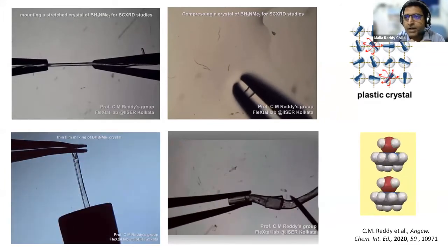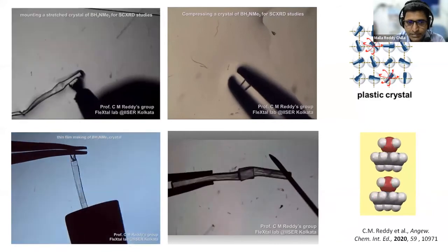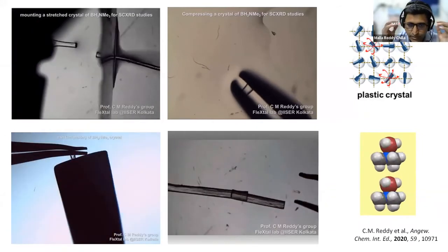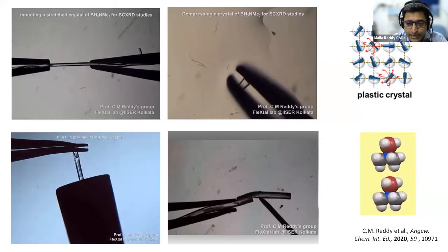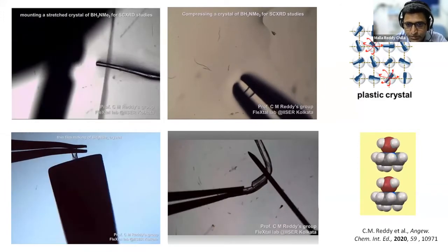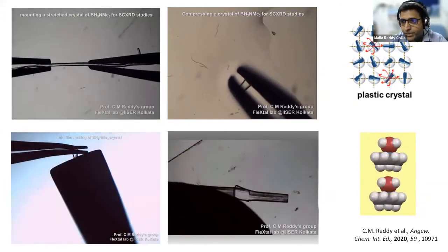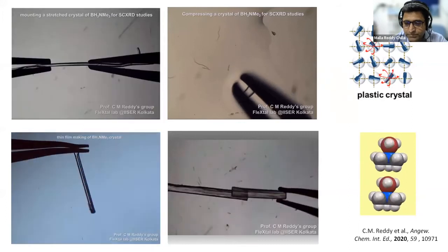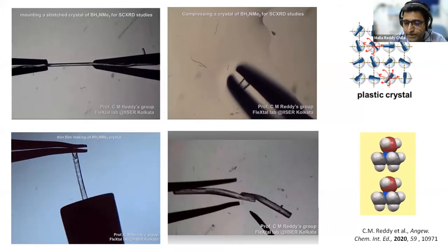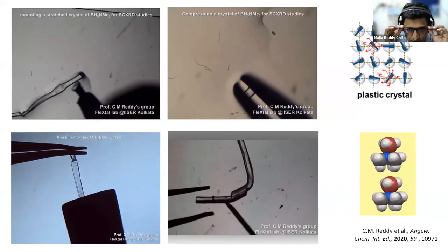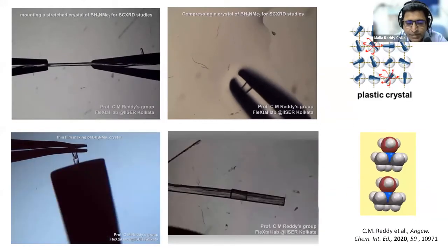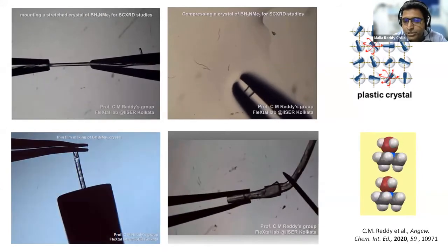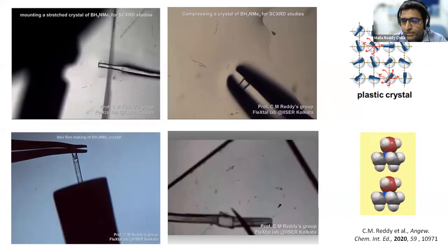For example, if you take a copper wire, unlike plastic molecular crystals, you can twist it, you can make a thin film, so they are very ductile, right? Highly plastic metals, particularly at higher temperatures, you can shape into any shape, but that was not seen in molecular crystals. Although people have studied certain crystals called plastic crystals, where you have orientational disorder in the solid state, and they showed extreme ductility and malleability, the structural property was again not looked at from the crystalline point of view.